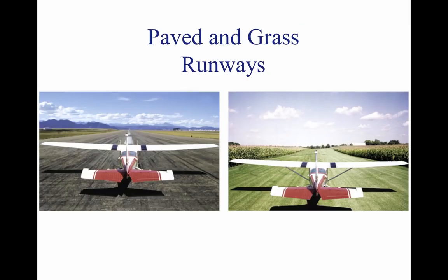Runway surfaces vary widely from one airport to another. The runway surface encountered may be concrete, asphalt, gravel, dirt, or grass. The runway surface for a specific airport is noted in the Airport Facility Directory, AFD. Any surface that is not hard and smooth will increase the ground roll during takeoff. This is due to the inability of the tires to roll smoothly along the runway.